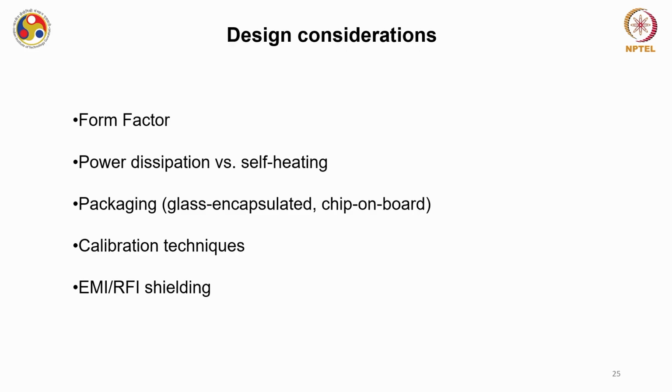So if you want to design a new NTC thermistor, one design consideration is the form factor, because you have to understand for what application you are developing this NTC, what should be its size, what should be its shape, and all those things. Then power dissipation versus self heating is another important thing to be considered while designing these sensors. Then packaging of these thermistors is very important.